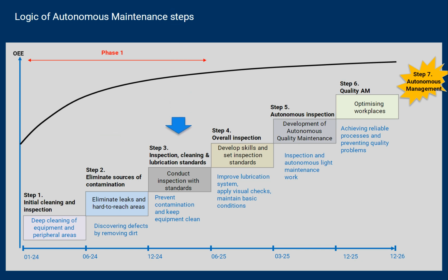Step 3. Standardization of cleaning, lubrication, and adjustment. The purpose of the third step, called standardization of cleaning, lubrication, and adjustment, is to educate operators on lubrication practices, identification of points and surfaces requiring lubrication, and establishment of standards for the lubrication and adjustment process. Additionally, improvements are implemented to facilitate inspection and lubrication, and efforts are made to further optimize the times established in the provisional standard.